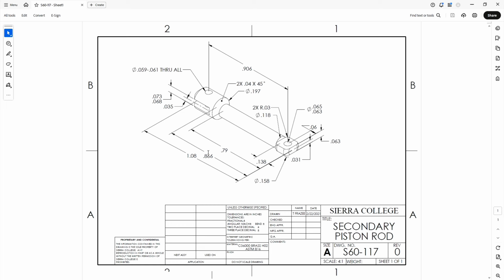similar features. So we want to set up our model to make sure that it's easy to change. Basically, we have this same connecting feature in B2 where it has the through hole in the slot, and then we have a common profile of the outside, and the opposite end changes, and the length of the rod changes. So if we set up this model correctly, we should be able to make the dash 143 and 145 much quicker. So here we go.